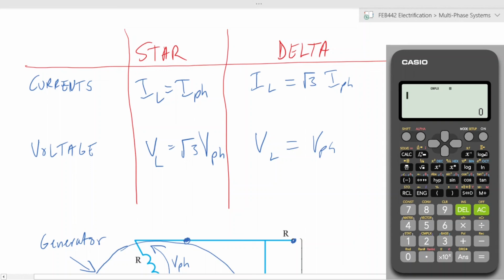One interesting concept in Kenya, our phase voltages are 240 volts, right? The voltage that you get when you connect your charger to the socket is 240 volts. And an interesting thing you will see is 240 times root 3 will give you 415. And if this figure looks familiar to you, it is because 415 is the line voltage of cables that are supplying power.